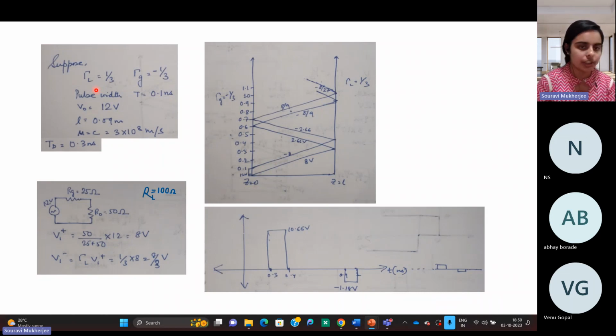You know the definition. So you know the reflection coefficient, you know RL, and by that you can find the characteristic impedance of your transmission line, and that turns out to be R naught equal to 50 ohm. If you know the reflection coefficient and you know RL, you can find R naught.